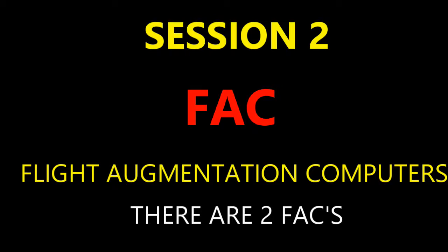Okay. Speed's important. Remember I mentioned speed and how we're talking about aircraft energy. When we're talking about current speed, we're talking about the acceleration rate as well, right? So here we're talking about the function of the FAC. We're talking about speed computation and display. That's going to be on the PFD, the primary flight display, and it's also going to show the speed limits, and those are going to be sent to the FMGCs.